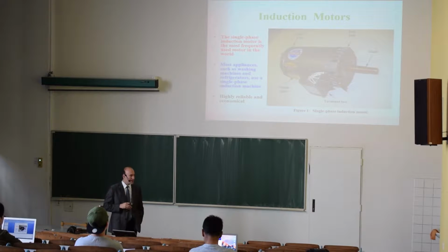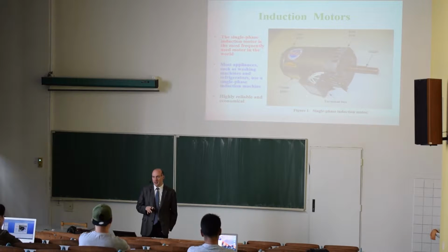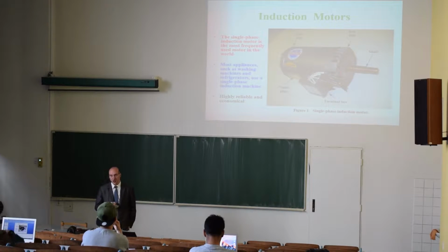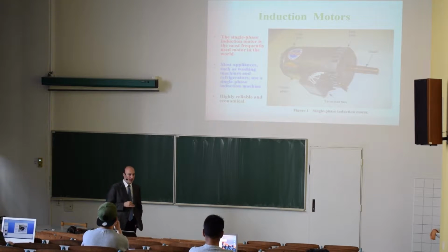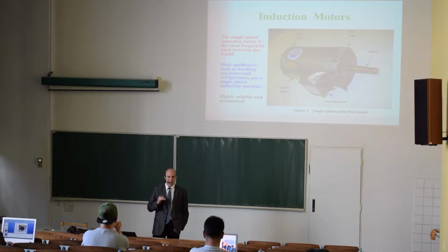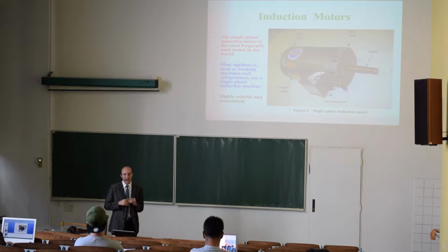The induction motor from the outside looks the same whether it's a 3-phase or a single-phase motor. The reason why an induction motor is so common is that we can very easily control the speed with today's electronics. It doesn't require any maintenance, so virtually all electric appliances that you can find will use an induction motor, with the exception of handheld tools, because handheld tools require low weight, and we will need a different kind of motor for that.